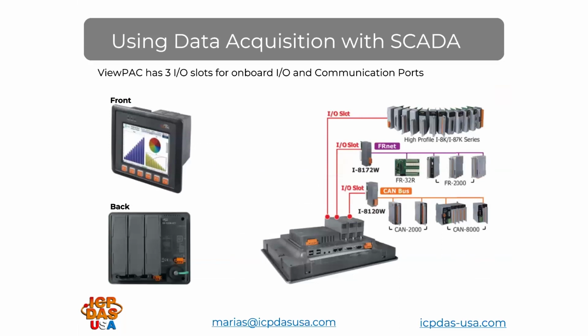There are 3 I/O slots on the back of the ViewPAC controllers, and those can be used to add communication like CANopen, J1939, DeviceNet, RS-232, RS-485, cellular connectivity, Ethernet ports, or analog and digital inputs and outputs, or motion control.